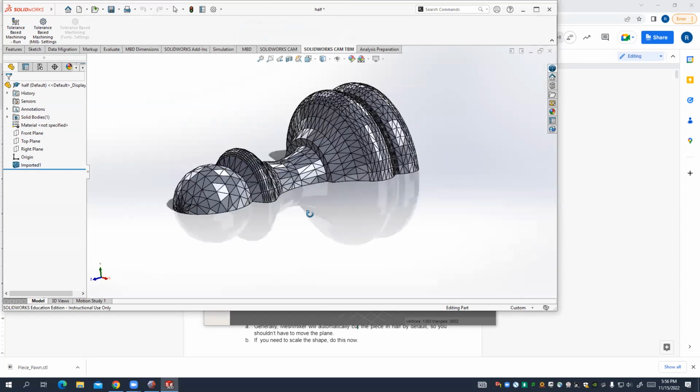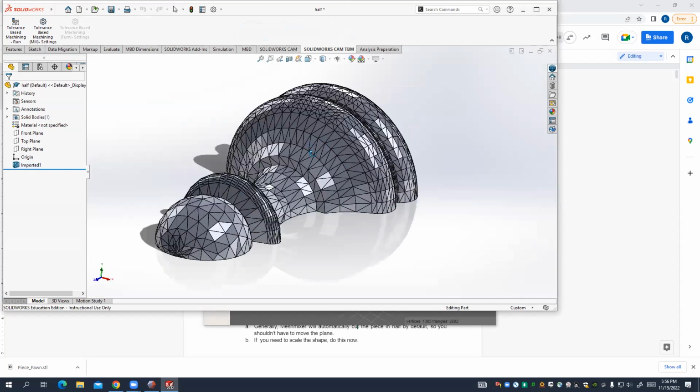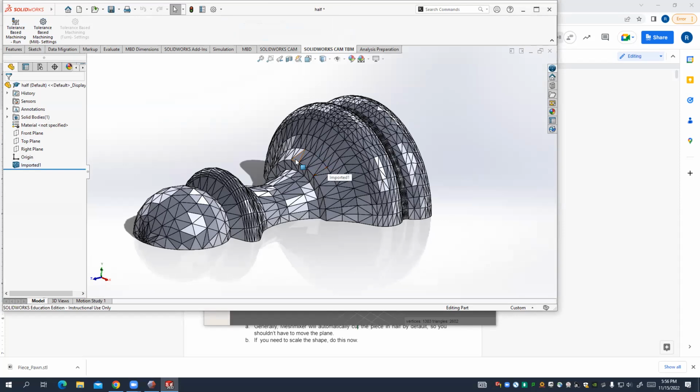As a quick introduction, for anyone who hasn't used it yet, this is SolidWorks. It's 3D CAD software. You can use it to make all sorts of parts and assemblies. The important thing to know for today is that it's based around sketches and extrusions. We'll make 2D sketches of the geometry we want, and then extrude it outwards to create 3D geometry. Once all that's done, we'll be able to save it as an STL and send it to the 3D printer.